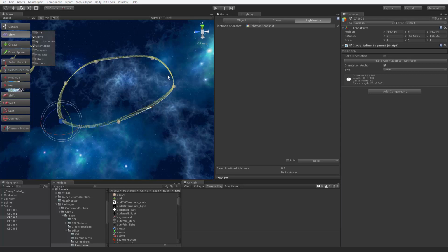As you remember, in dynamic mode, orientation is decoupled from segments between the control points and is instead smoothly changed from one anchor to the next. Paths which anchors divide splines into are called anchor groups. In our case, we will be looking at an anchor group spanning between control point number 4 and the end of the loop. In other words, control point number 0. Other anchor groups contained in our spline span from control points 0 to 2 and from 2 to 4.